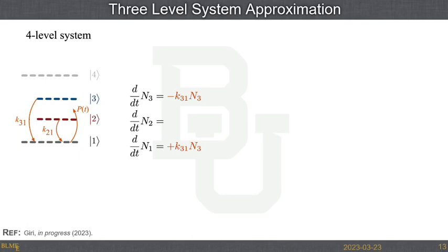And then I can do the same thing for this 2-to-1 transition, and then I have my laser that's coming through here that's going to take electrons from here and dump them up. Depending upon the wavelength, I'm either going to populate this 2 state, those are my erbium arsenide states, or I'm going to populate this 3 state, which is my conduction band. If I come with a high enough photon energy, I'll make that 1 electron volt gap here and be able to populate the upper state, and then I'll take some population out of the lower state.